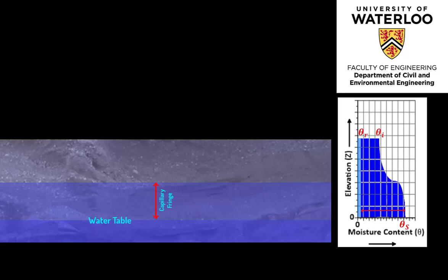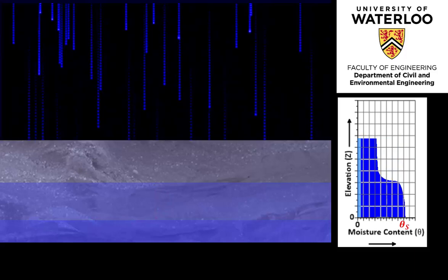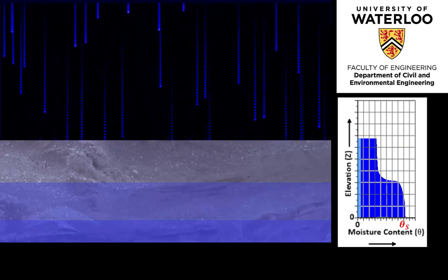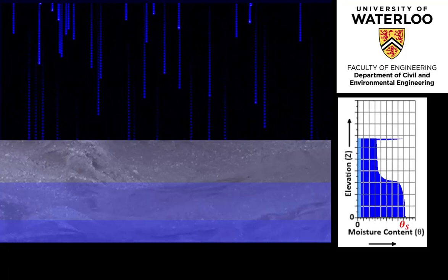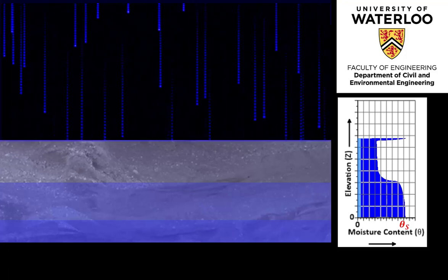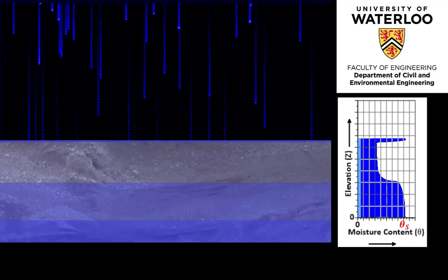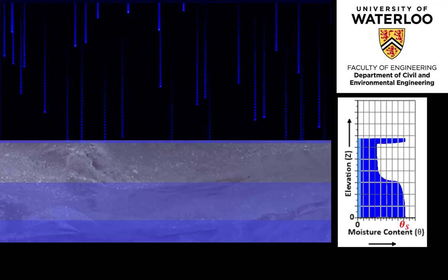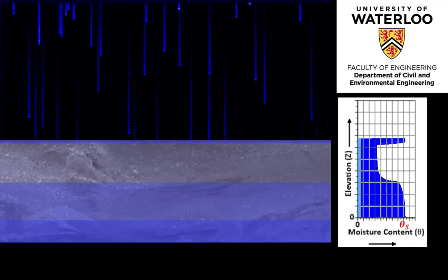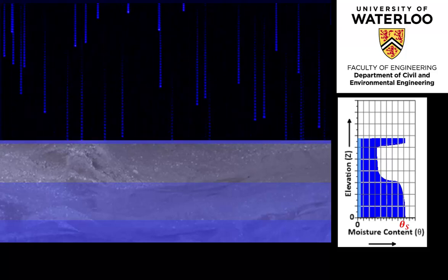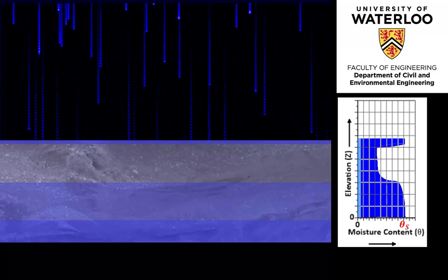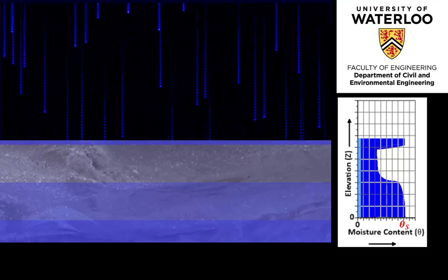Further, the shape of the soil moisture curve will vary based upon the initial moisture conditions and recent infiltration/percolation past, yielding a notably nonlinear relationship. The ring infiltrometer test will emulate a precipitation event, whereby producing a saturated condition at the ground surface, and thus a condition of theta S, which will propagate vertically downward through the porous media, which is known as percolation. Although the specifics of the soil moisture curve will not be quantified using this testing method, the maximum rate of infiltration from the ground surface into the soil will be estimated, and how this rate varies with time quantified.